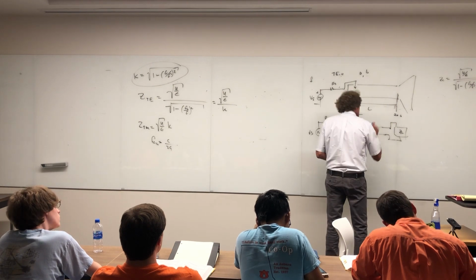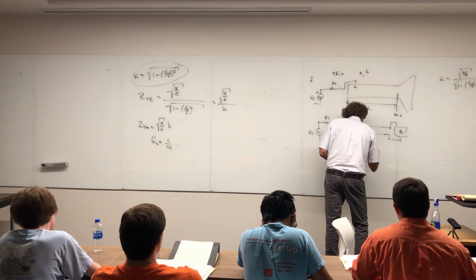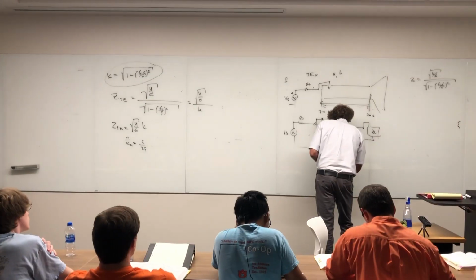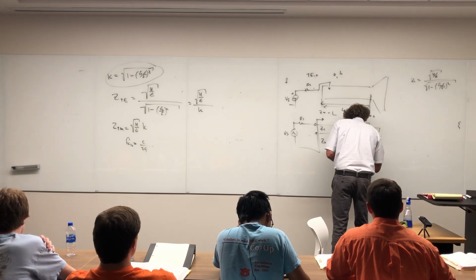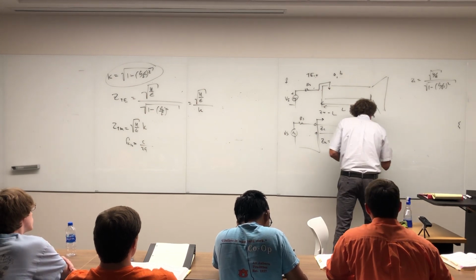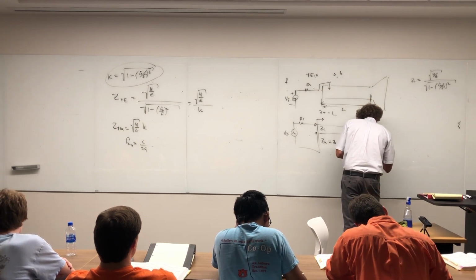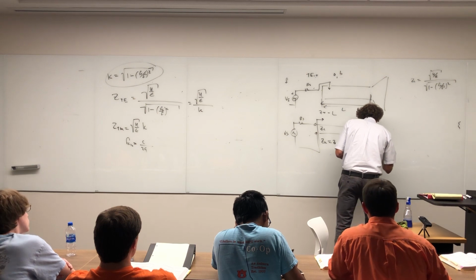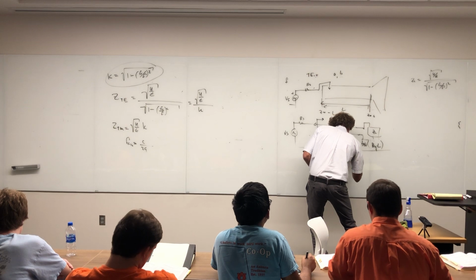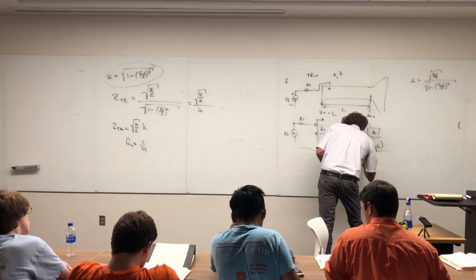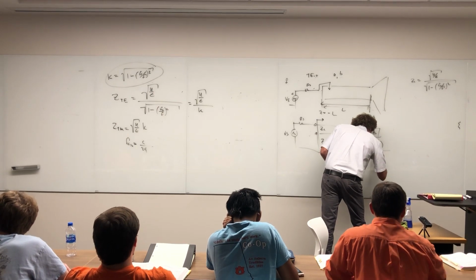So this is going to be equal to that characteristic impedance, ZC 1-0 mode, times ZL plus jZC 1-0 times the tangent of beta in the guide times L, over ZC 1-0 plus jZL times the tangent of beta in the guide times L.